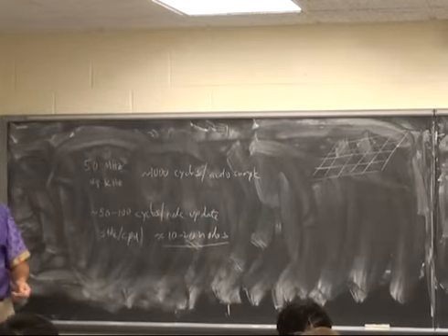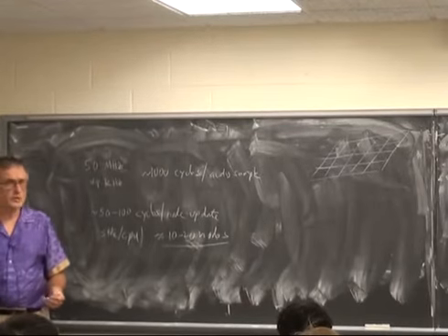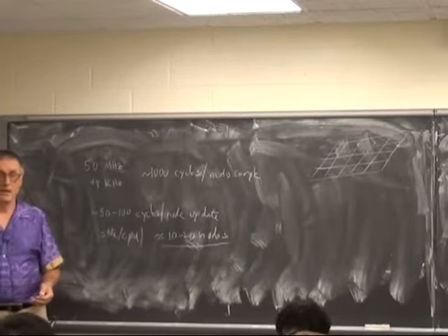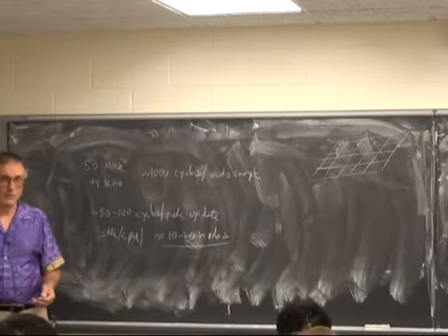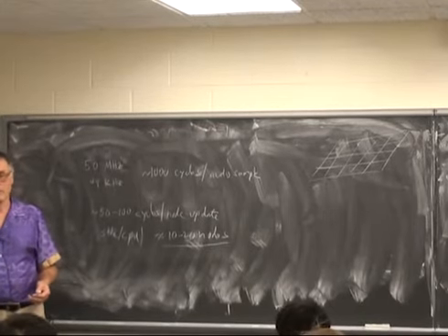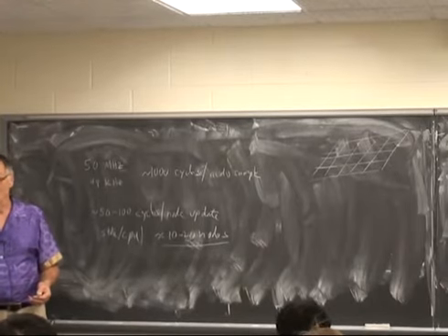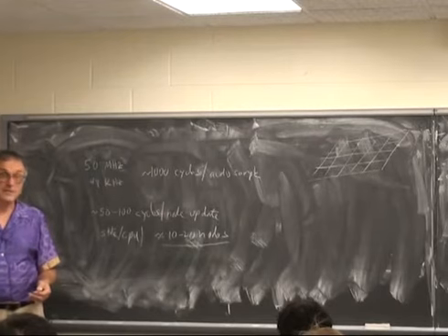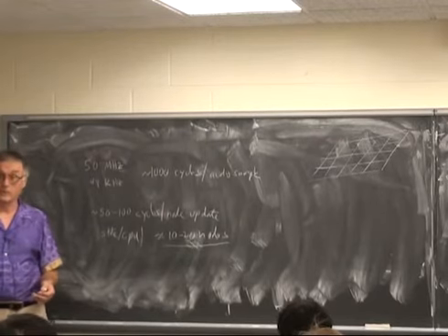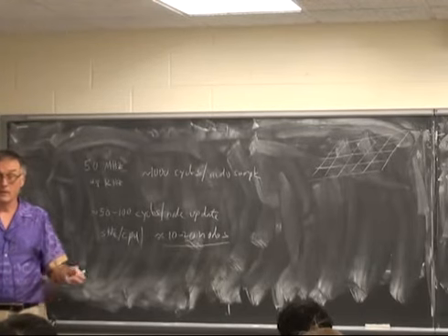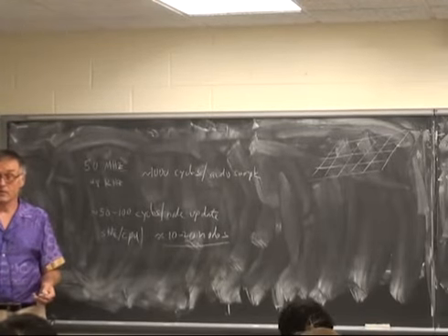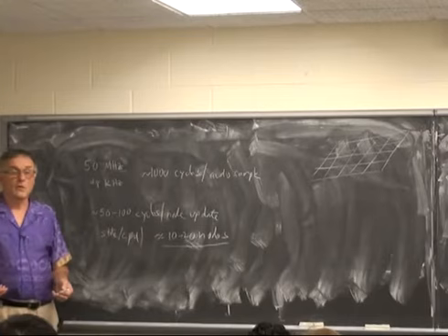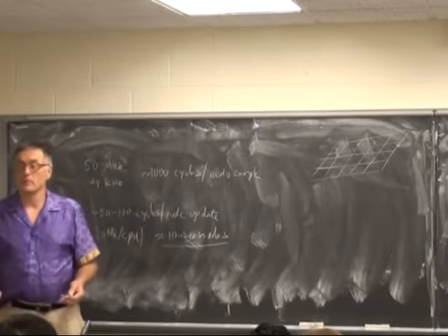And then you could have a uniprocessor running, but with a weird instruction set, with instructions like add 4 nearest neighbors together. You might also be able to figure out a way of duplicating memory, so you have multiple copies of the grid, so that you can do 4 memory accesses in one cycle off of 4 copies of the grid. Because you got lots of memory, right? You got the 104 M4K blocks. Why not make multiple copies of the grid so you can do multiple memory accesses at once?